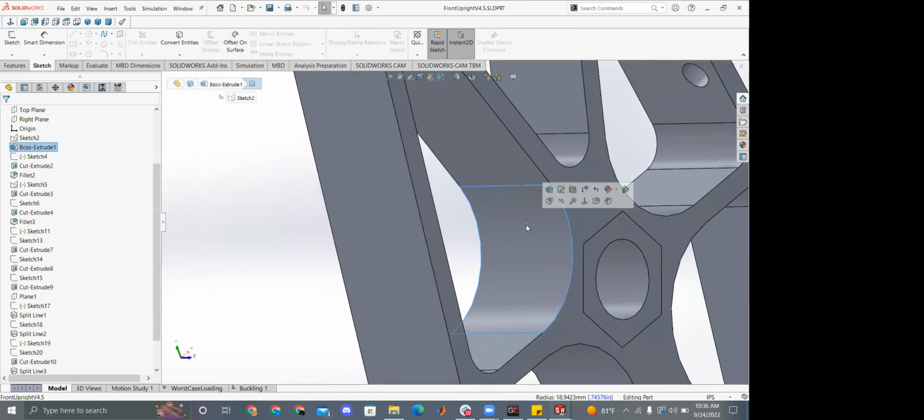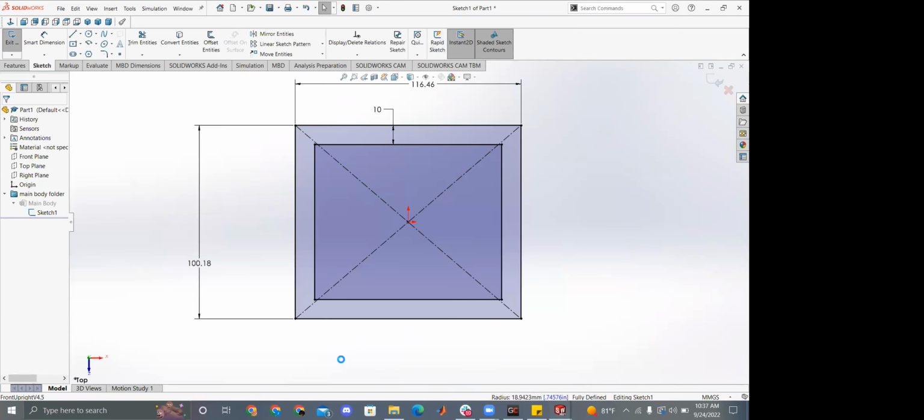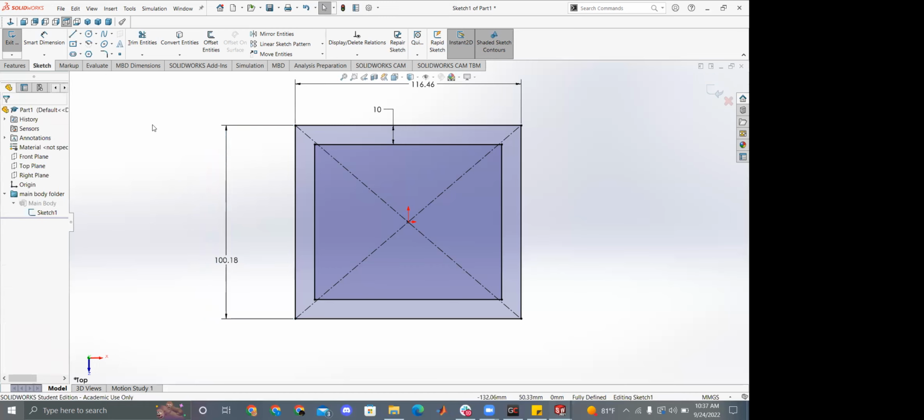A fillet is basically taking a circular cutout and putting a radius on every single corner, so you avoid that stress concentration. There's a couple ways to do fillets. You can do them in sketch, or you can do them on the body. I can show you both. Generally, it's a lot better to do your fillets on your body, although there are some cases where your fillet radius could cause some errors that you want to do it in the sketch just to make sure, or if you want to visualize something with a fillet, because it can be hard to do that without an actual fillet there. It's fine to do it in a body, but in general, you want to do it as a feature.